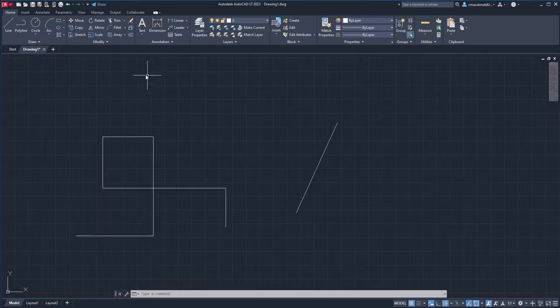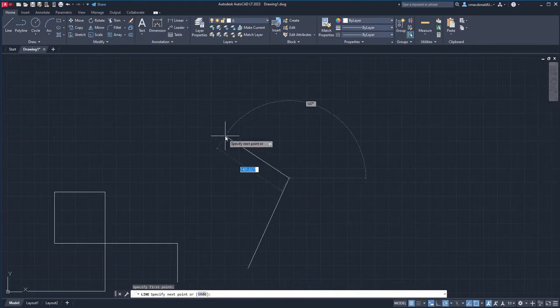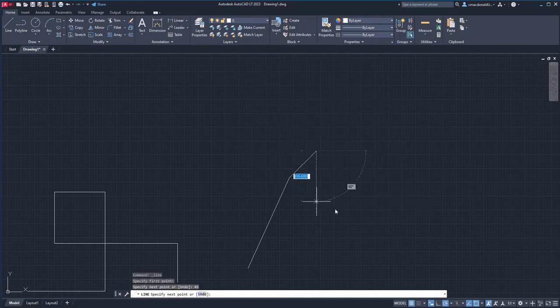If you want to produce additional lines in addition to that one, you can very easily. So again, using dynamic input, we'll call this one 700 in length. Hit the tab key one more time, hit 45 degrees, type 4 and 5, and hit enter. And then we can add as many unique angles as we wish. Here, let's try a little bit of a different one. Let's try one at 1500.